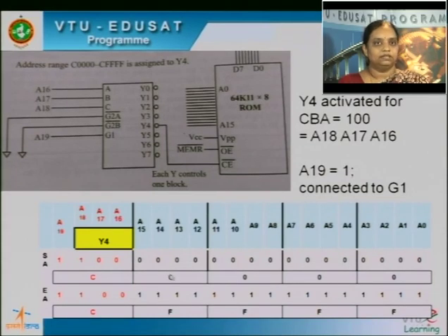So to compute the capacity of the memory, if the start address and end address are given, the procedure is to take the end address and subtract the start address from it. So here C 4 Fs minus C with 4 zeros gives me 4 Fs, and to this you add 1. So 4 Fs plus 1 becomes 1 followed by 4 zeros in hexadecimal, and that 1 is in the place of 2 to the power 16, that is 2 to the power 16.